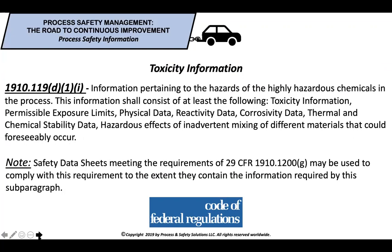So let's talk about the different parts. We're going to talk about the first part, D1I, first, and that's information pertaining to the hazards of the highly hazardous chemicals in the process. This information shall consist of at least the following: toxicity information, permissible exposure limits, physical data, reactivity data, corrosivity data, thermal and chemical stability data, and hazardous effects of inadvertent mixing of different materials that could foreseeably occur.